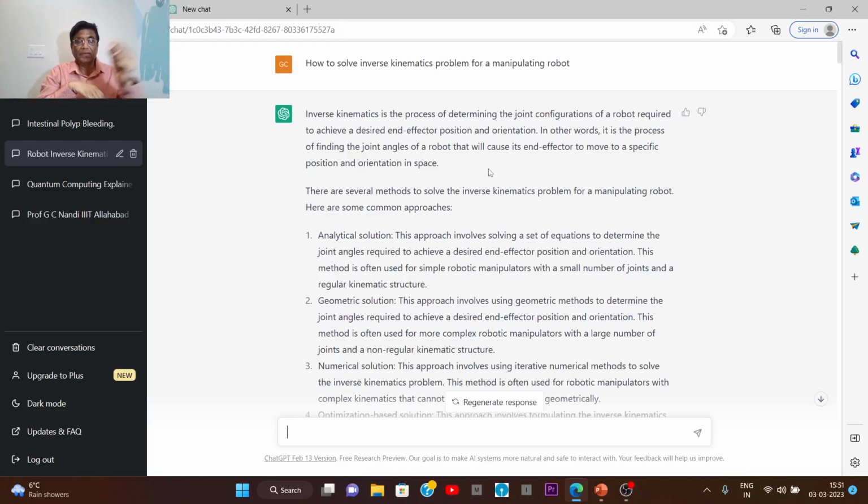An inverse kinematics problem is when I ask my hand to reach somewhere. I specify this as an input: X, Y, Z, alpha, beta, gamma. Okay. Then the robot needs to know, or my hand needs to know how to reach there. And this is called inverse kinematic solution. And of course, for those who do not know, in this inverse kinematic solution, the mapping between Cartesian space and joint space is nonlinear. Why? Because for reaching here, there are so many different arm configurations. Even I can move my hand like this.